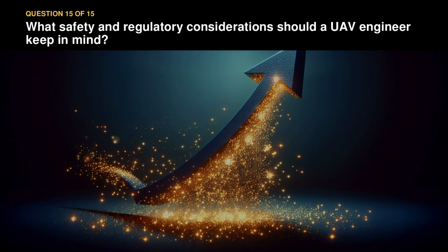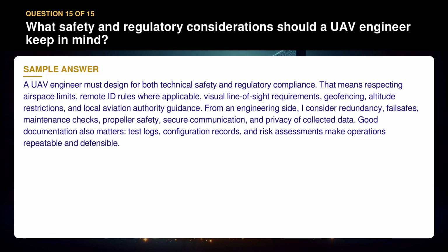Question 15. What safety and regulatory considerations should a UAV engineer keep in mind? A UAV engineer must design for both technical safety and regulatory compliance. That means respecting airspace limits, remote ID rules where applicable, visual line of sight requirements, geofencing, altitude restrictions, and local aviation authority guidance.